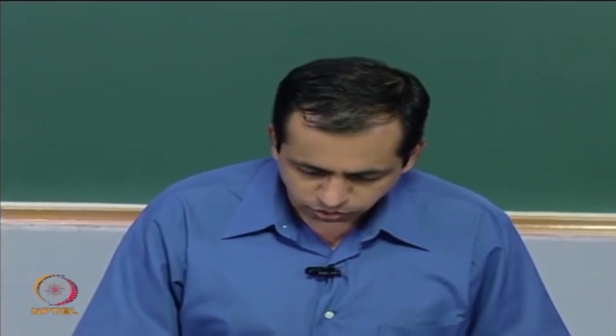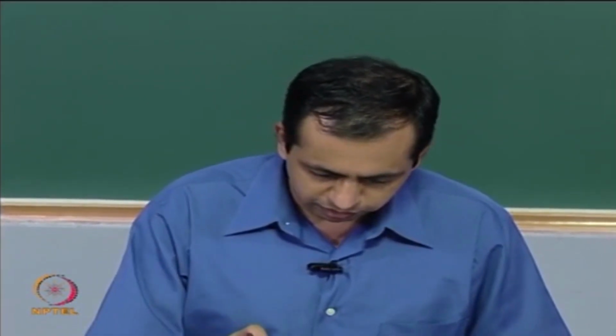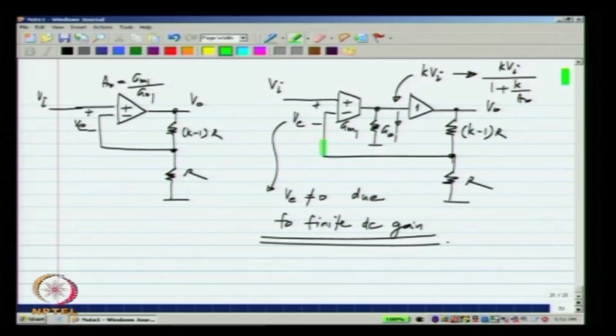Now, what is the desired outcome? In a negative feedback system, the feedback quantity here must be exactly equal to that quantity there. In fact, with an ideal op amp that was happening, right. If you had an integrator without a finite DC gain, this is what was happening. Okay. There should be a capacitor here C1, that is what was going to happen. What we can do is, this is the actual value, we can compare it to the desired value and based on that control the current that is flowing there, okay, using an integrator.